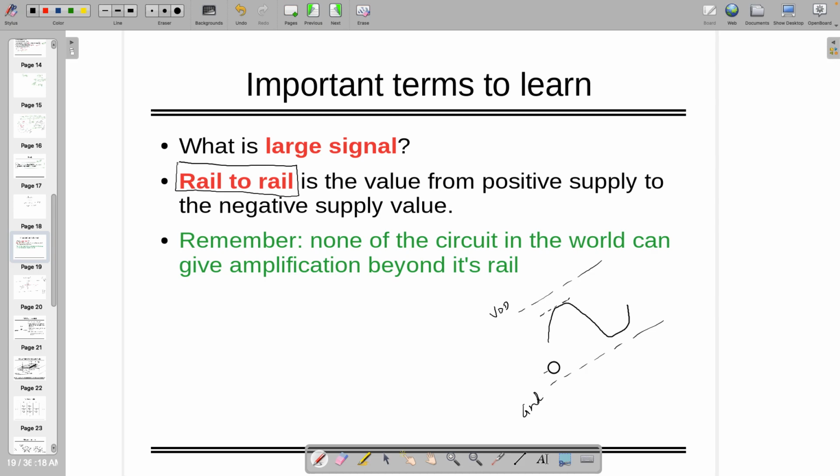This is happening because of lots of problems, because of threshold voltage and other things. So it will not reach exactly VDD. So we have to make circuits which are reaching rail to rail or having full swing. In this figure, the red color is rail to rail, whereas the black color output is not rail to rail.